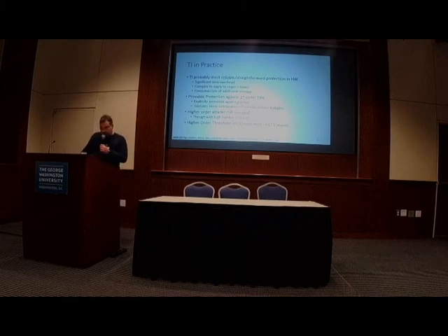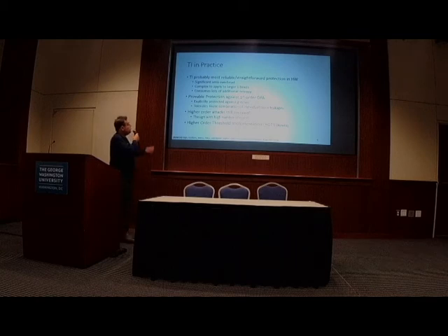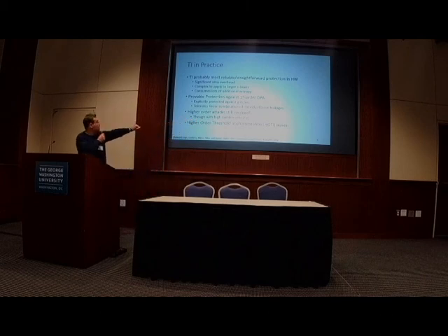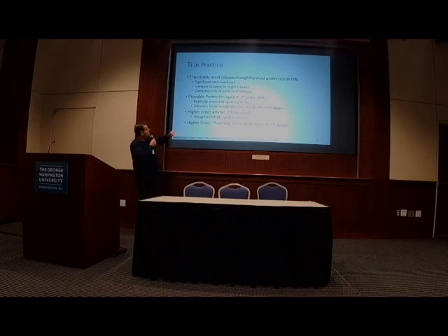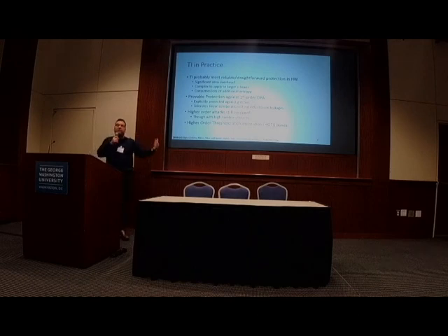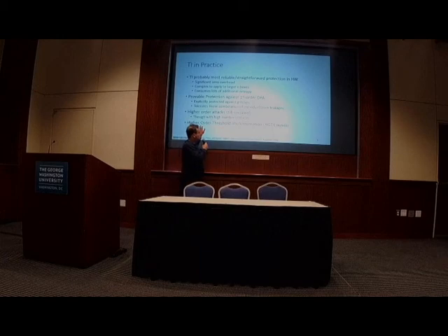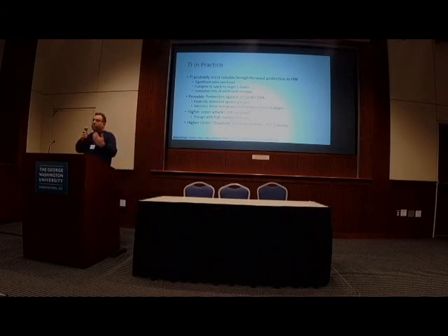And there's protection against first order DPA, and it tolerates linear combinations of leakages. Higher order attacks still succeed if you use moments and so on, but that means you have to use a lot more traces, of course. So there's a trade-off. And there are new results now, where threshold implementations are proposed to prevent higher order leakage. So you do higher order threshold implementations.